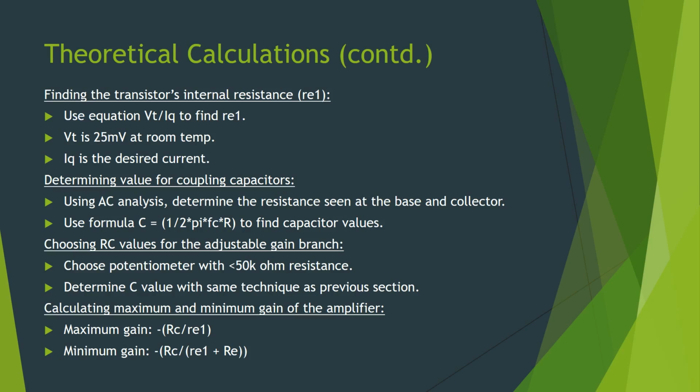For the output capacitor, you do a similar calculation. And by the way, the 50 is just a cutoff frequency, which I chose somewhat arbitrarily, which is why it's okay to just adjust it, because we're going to be filtering DC whether it's 677 or 500, same thing. For the output capacitor, we're looking at the same equation, 1 over 2 pi times the cutoff frequency, which in this case is 50, but this time the resistance value is different.